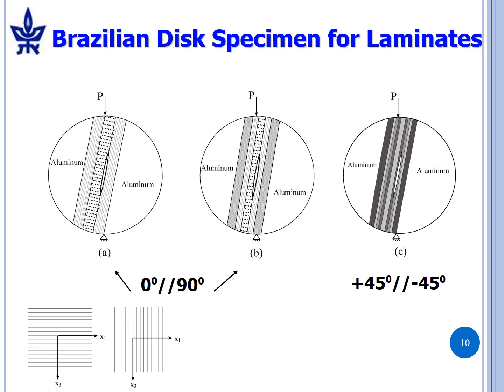So we have a number of plies. Plies are about 0.25 millimeters thick. And here we have a layup where again we have 0/90, but we have 0.5 millimeter layers, and then we have outer stiffening layers. One would hope that one would obtain the same energy release rate in both cases for the same mode mixity. And indeed that occurs: we did find that it didn't matter what the layup was as long as the interface was the same. And then here we have a variety of plies and layers.